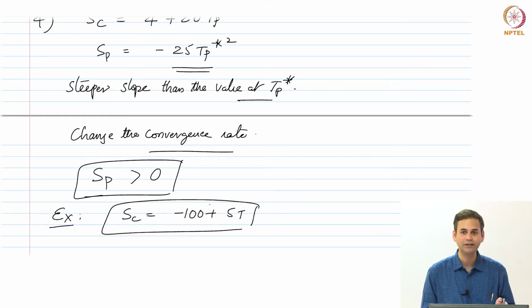Like, how do I deal with this thing? To deal with these kinds of problems, we have something known as relaxation, which is kind of artificially changing the diagonal dominance. We will come to that a little later. But you would not get a problem where it will be just 5t. You don't have a positive feedback loop physically possible. But as he said, you can have a different model, or a transient model where the source is switched on for some time and then switches off before it reaches infinite. That is possible. For these kinds of problems, we would have something known as under-relaxation, where we change the coefficient of AP by certain amounts to deal with the diagonal dominance issues.